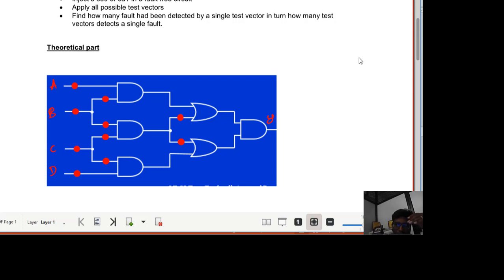The fault is a manifestation of a manufacturing defect that would have happened during manufacturing. If you consider a complete RTL, this RTL would have gone through multiple verification, that is logic level verification and functional verification, through the complete process before going for manufacturing. Even then, when it is sent for manufacturing, there is every possibility that a manufacturing defect could exist. Possibly there could be a short between the wires, or an open in the wire, or a rupture of the MOS device.